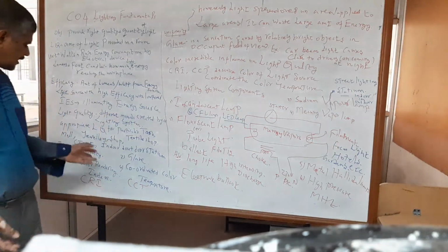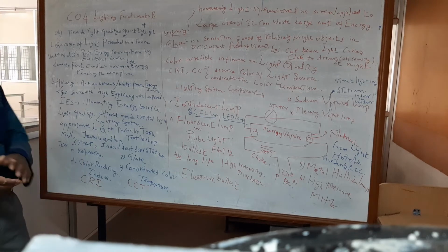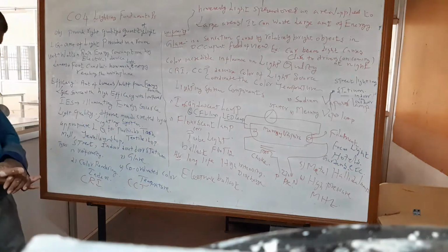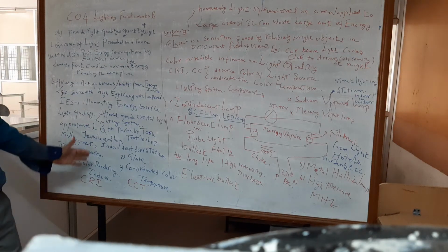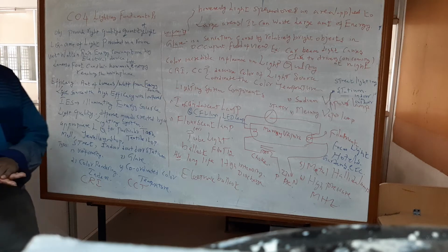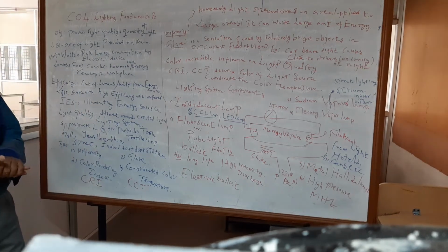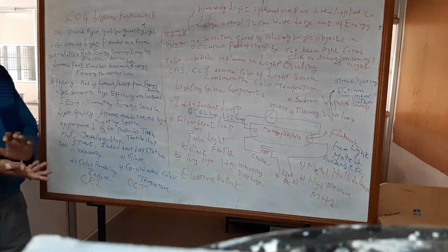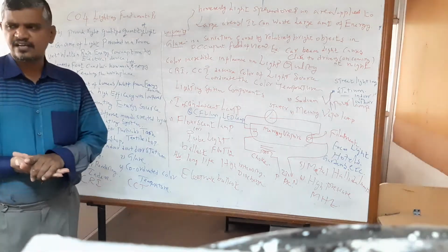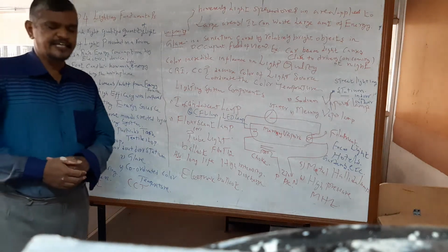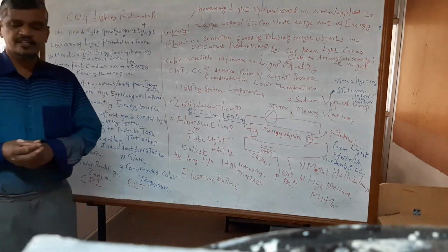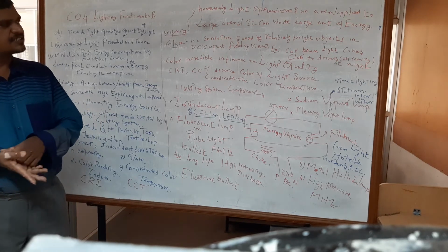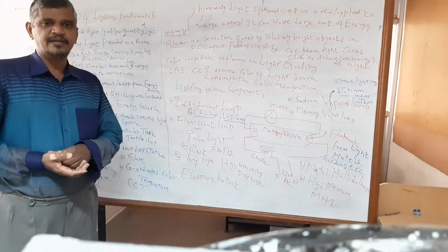The lighting quality parameters are uniformity, color rendering index, glare and correlated color temperature, that is CRI and CCT. Four types are available. First, uniformity is one of the properties of light quality. Uniformity is how evenly the light spreads over an area, and it can apply to large areas. Suppose we apply light to large areas, a large amount of energy waste can take place in the system.